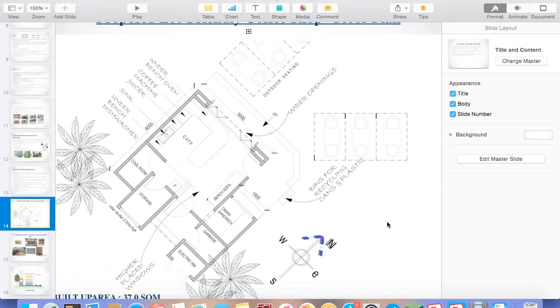This is the north, as you see, this is the northeast direction. We have tried to put outdoor seatings and everything over here. They are wide opening, foldable doors on the north side, so that there is ample sunshine and air from this direction, which won't be harsh sun rays, and we don't have to worry about the high temperatures in this area.